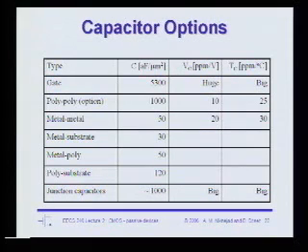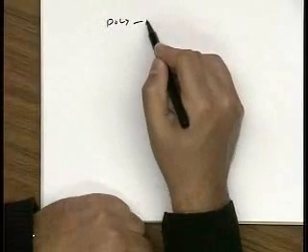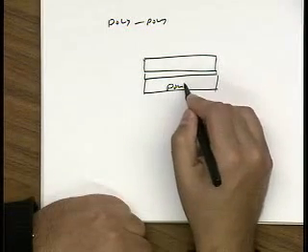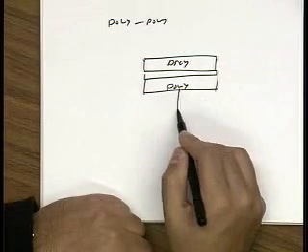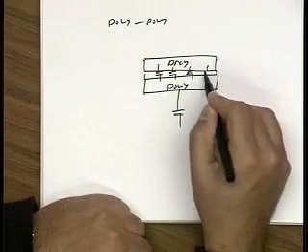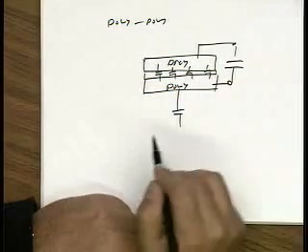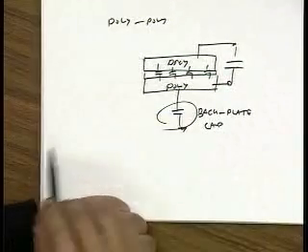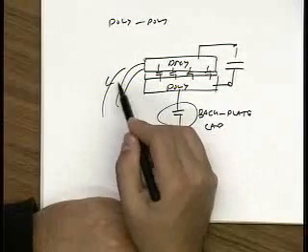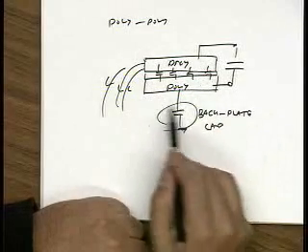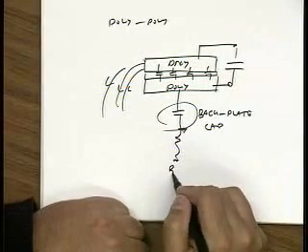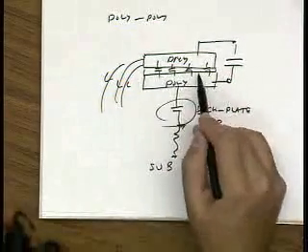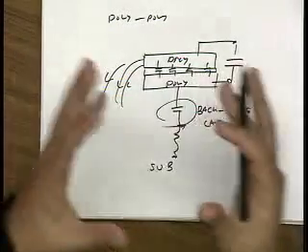So for instance, let's say I build a poly capacitor. Let's say it's a poly-poly capacitor. So I have a polysilicon, an insulator, polysilicon, and so I have my actual capacitance that I want, that's between these terminals, but I also have this backplate capacitance, which is a parasitic, right? The front gate is shielded, so you get a little bit of fringing fields from the front gate, but mostly it's the back gate that sees the substrate. Okay, so the higher the density I can make this capacitor, the thinner I make this oxide, the less this matters, because I can physically make it smaller.